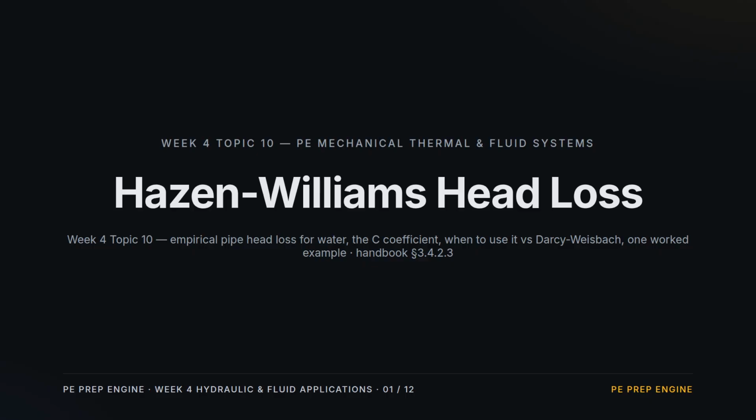Topic 10 of Week 4. Hazen-Williams head loss, the empirical shortcut every water distribution and fire protection problem leans on. No Reynolds number, no Moody chart, just one roughness coefficient called C. We'll build the formula exactly as the handbook prints it, decode its unit mix and its per-foot output, work an example, and lay out when Hazen-Williams is the right tool and when you must fall back to Darcy-Weisbach.